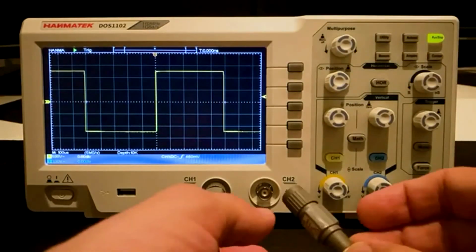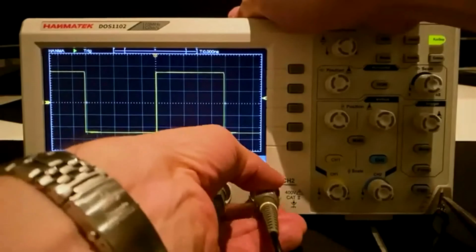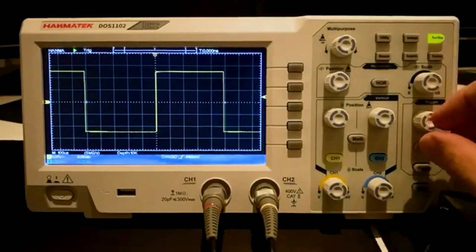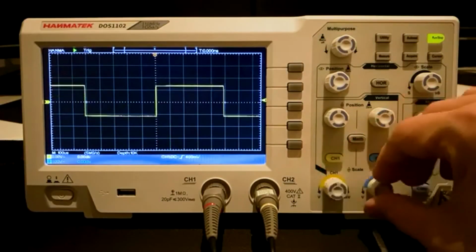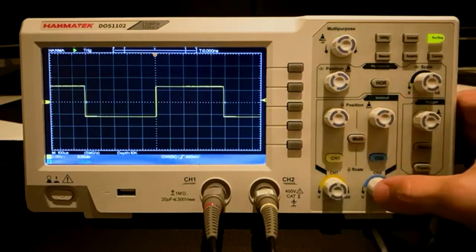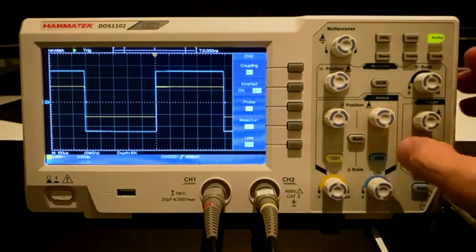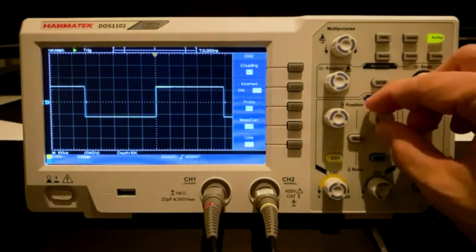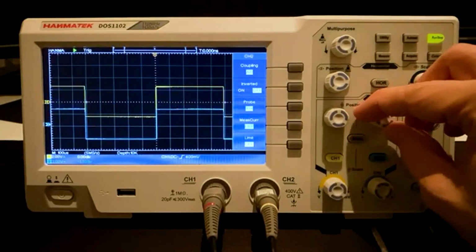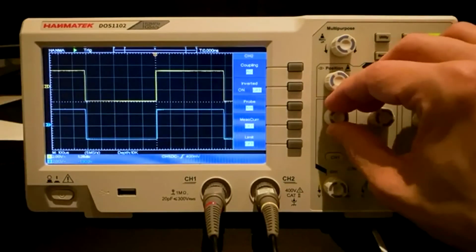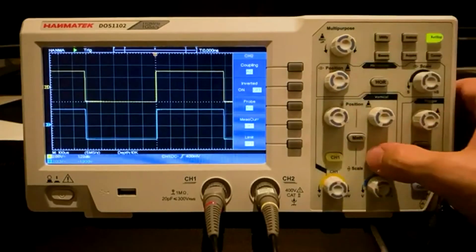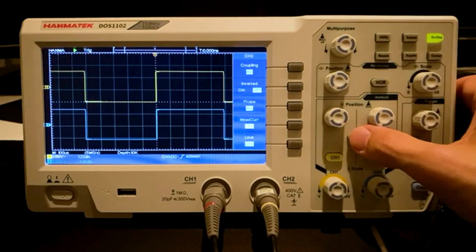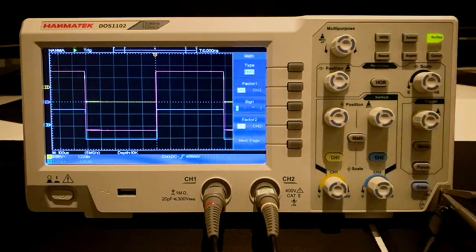With a math function, mathematical operations can be applied to the signal. Another signal is required for the test. Two signals from channel 1 and channel 2 are aligned with one another. The math function is opened by pressing the gray math button. A third signal is generated on the display.